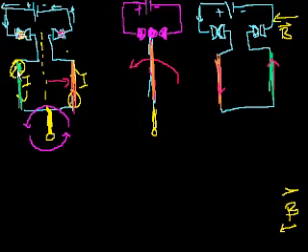Use your right-hand rule. The current is flowing down here. So if your magnetic field is coming to the left, then the net force is going to be down there, and it's going to be up there. And so we can continue indefinitely, and we solve our other problem, that we will never keep twisting these wires. So now, using the commutator, we have essentially created an electric motor. And remember, I drew that little thing. That could be like the axle, maybe that turns the wheels or something.